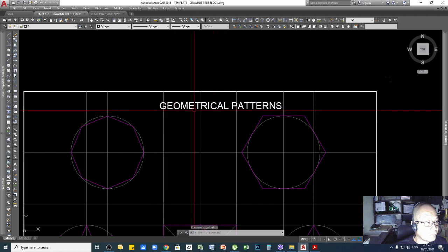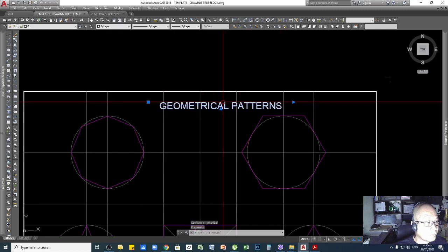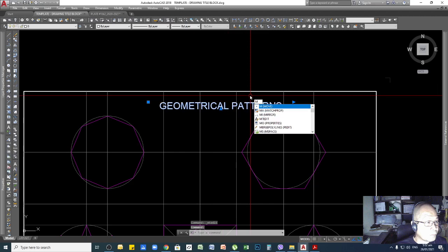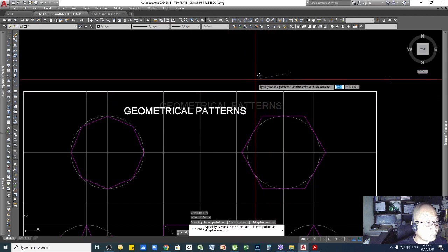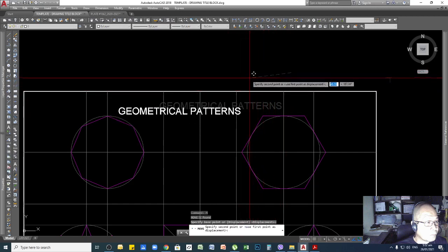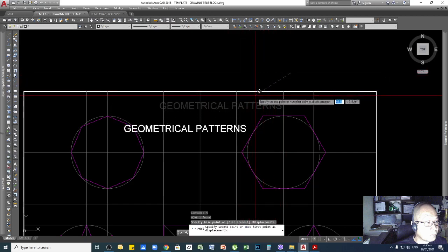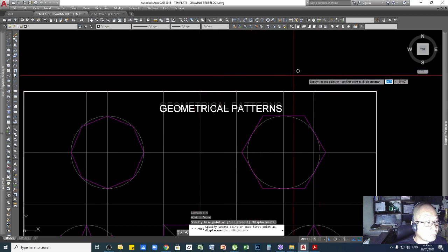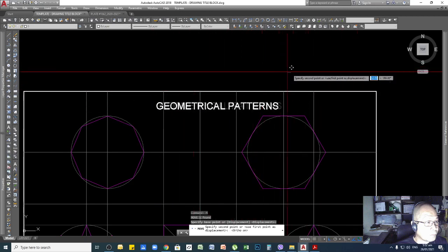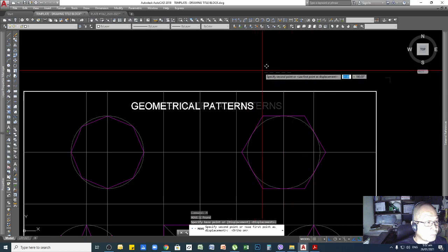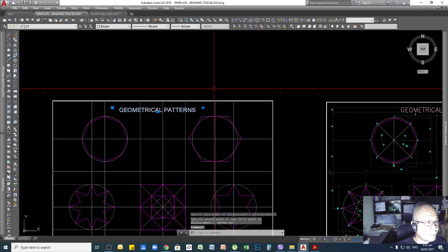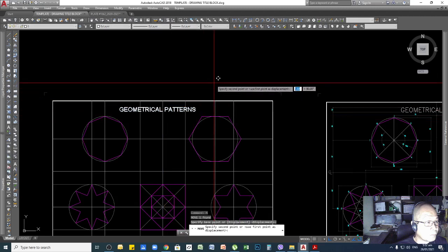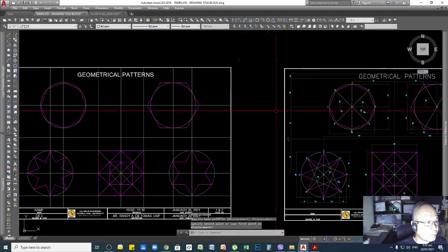box. So to make it at the center, just click, use the command move, and then move it. So you see, it's not on a horizontal lock position, so I need to press F8 again so that I can move freely on a lock position horizontally. Okay, so just estimate somewhere in the center like that. Okay, so if you find it a little bit down, move again, move upward like that, and you're done.